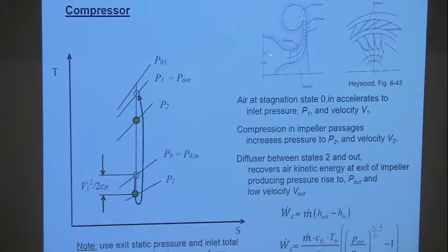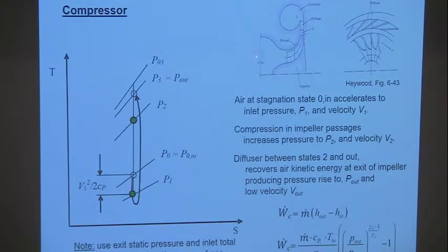Here I have my flow entering from the environment, let's say, through a converging nozzle. I then go through the impeller, with the rotating blades. Then I go through a diffuser section to remove the kinetic energy and convert it back to a total energy state.